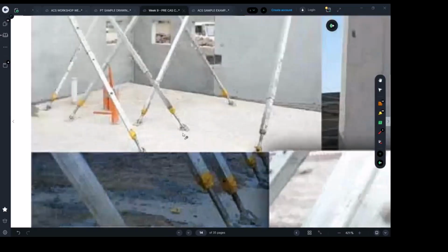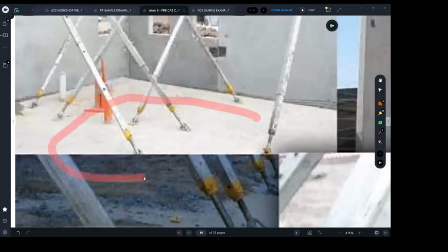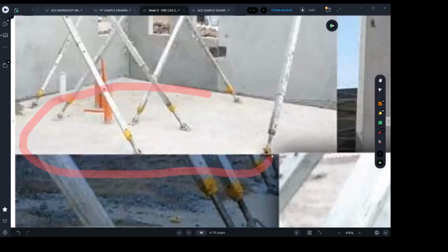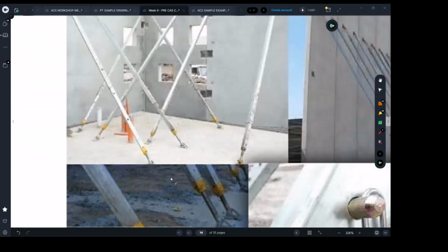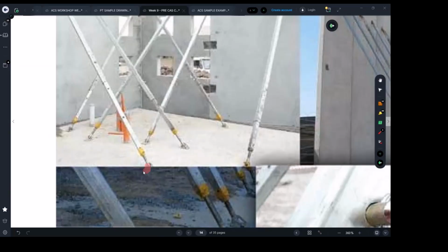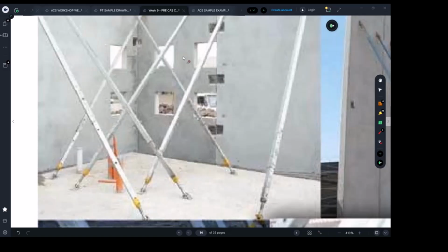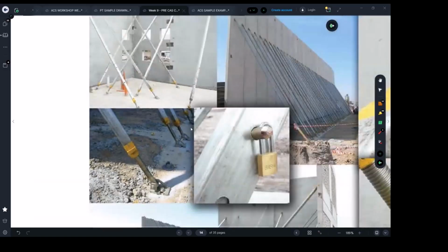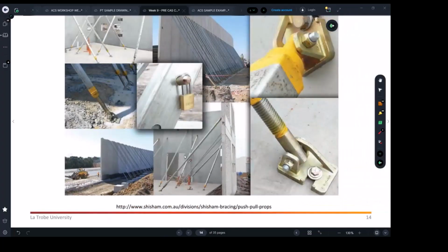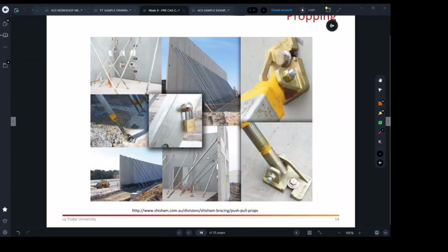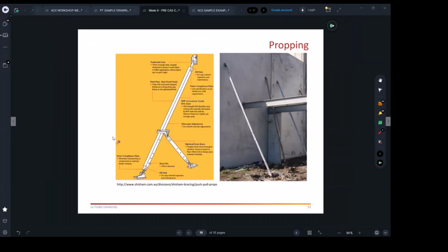Sometimes it's acceptable to fix into a slab already, like an industrial slab, and that was okay with the architect because they will have a special finish on top of it. Sometimes it's not, because the architect was after a polished concrete finish, and then these many holes and fixings may compromise that aim. So it really depends. The point here is you need to go through these considerations and these thoughts, because if it's missed, you may have issues and you may need to provide compensation for the arrangements.